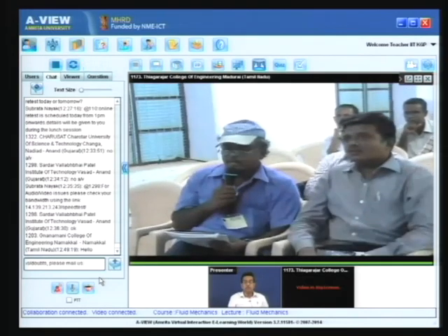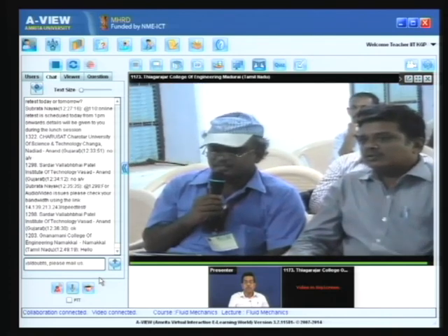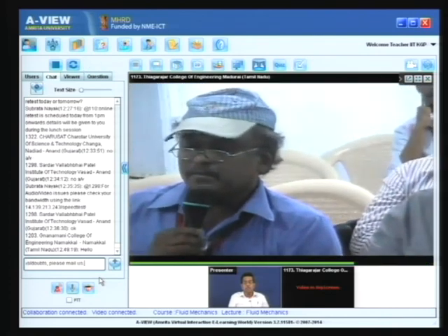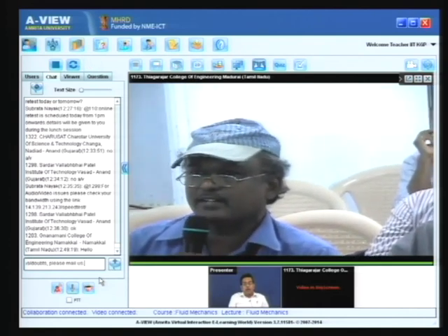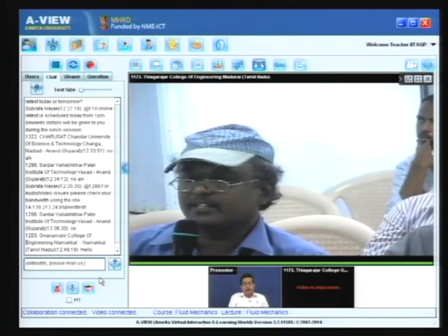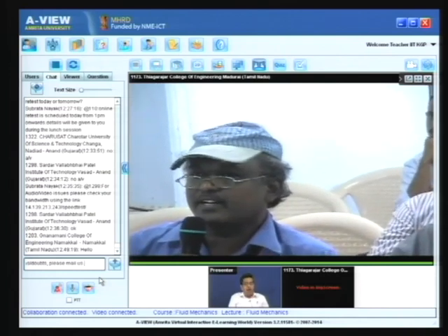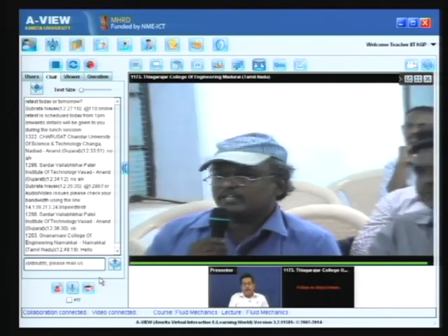Sir, while you were teaching pipe flow, you showed us the Moody chart. The epsilon value for PVC pipes and stoneware pipes was not shown there. It was for concrete and cast iron. How do we get that data? I do not know whether it was in the diagram or not, but you can take it from any handbook. This is practical information, there is nothing related to fluid mechanical concept that you can get from it.